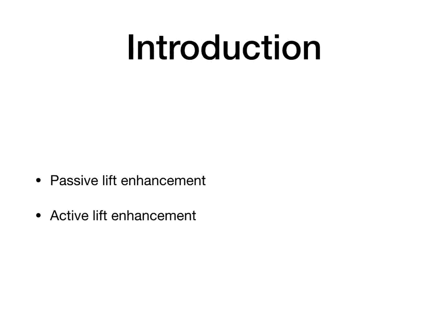Introduction. So lift enhancing devices, the value of maximum lift coefficient were used to determine the takeoff and landing distance. These assume the use of some type of lift enhancing devices. Such devices provide a methodology for determining the three-dimensional lift and drag characteristics in a high lift configuration.